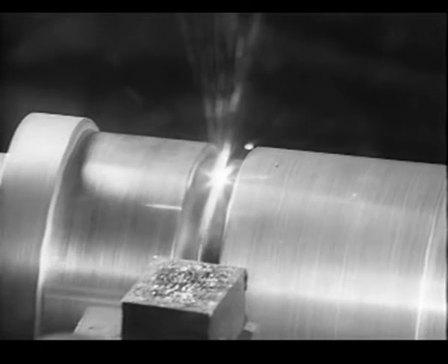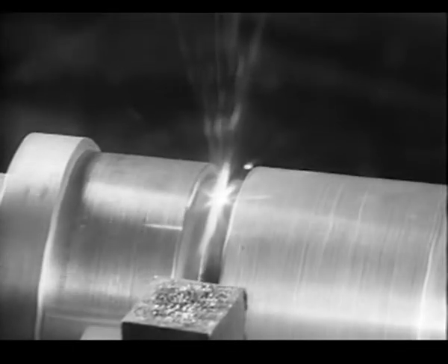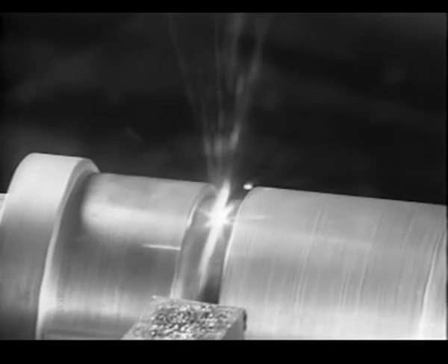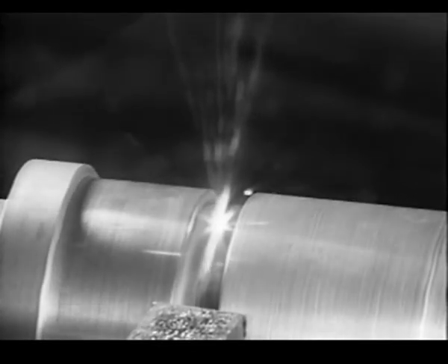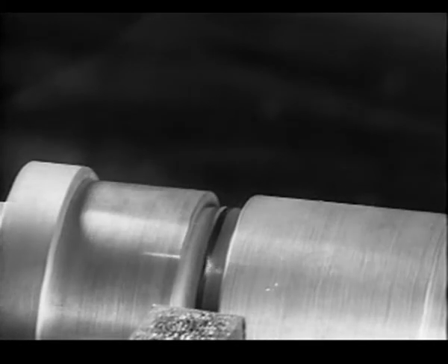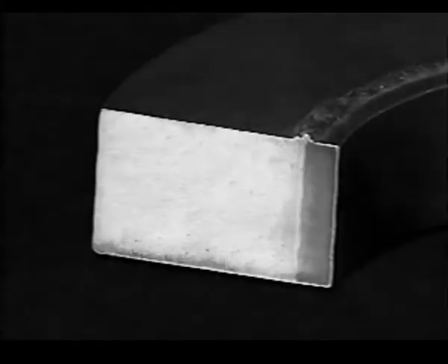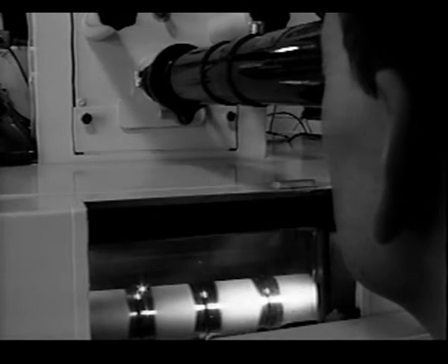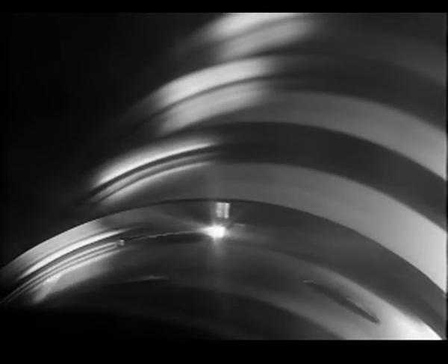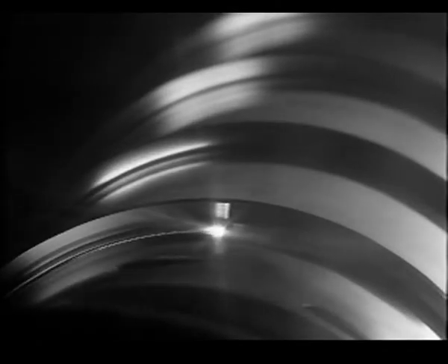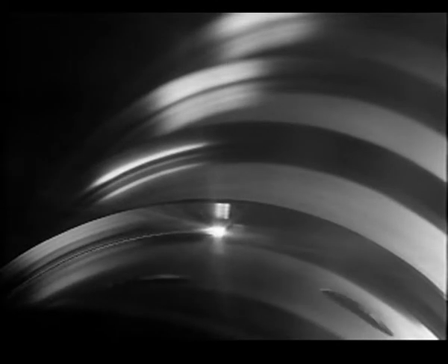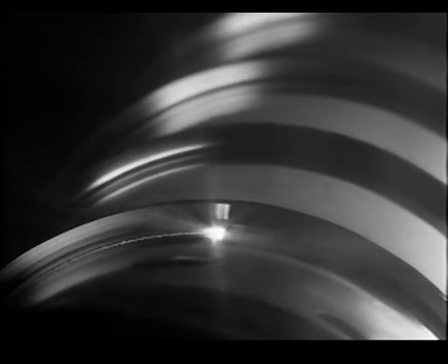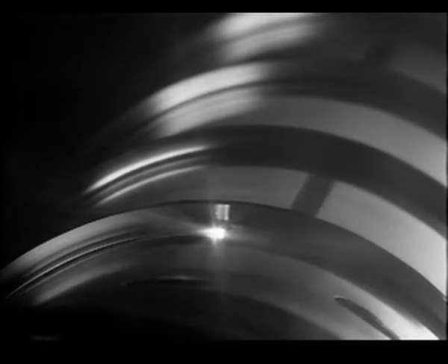or standard atmospheric pressure. Because of the intense and concentrated heat generated, total heat input is low, minimizing heat-affected zone size and part distortion. This also allows for the creation of extremely deep and narrow welds. Additionally, joints inaccessible by other welding processes can be welded. Virtually all ferrous and non-ferrous metals, thin or thick, can be joined. Welding speeds are fast, and filler metal is not generally required.